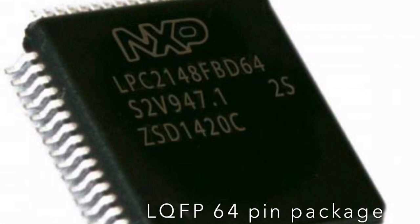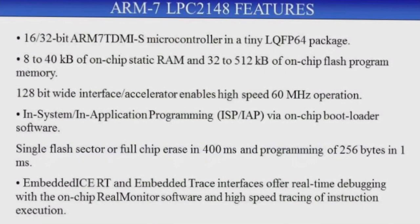Coming to the ARM7 LPC special variants, the features include the following. The first feature is the 16/32-bit ARM7 TDMI-S microcontroller in a tiny LQFP 64-pin package, with 8 to 40 kilobytes of on-chip static RAM and 32 to 512 kilobytes of on-chip flash program memory. It has a 128-bit wide interface or accelerator that enables high-speed 60 MHz operation. It has in-system or in-application programming via on-chip bootloader software.